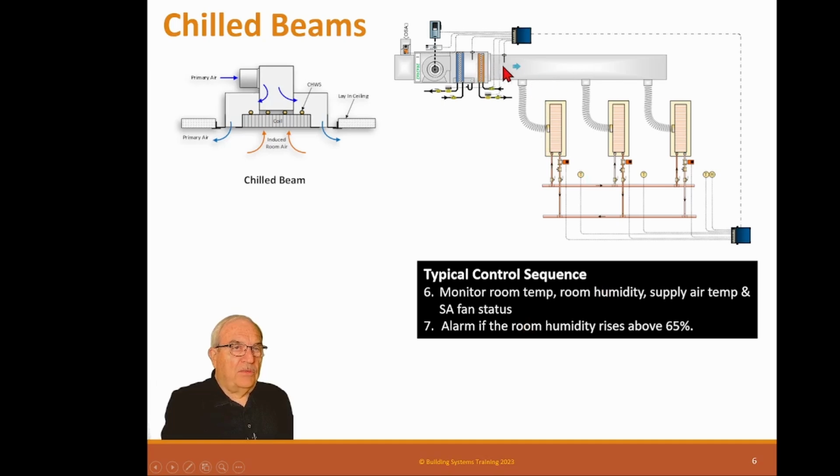Sometimes they have a little bit of a problem setting up the air handler system and how to tab it, because there's no way you can try to measure these little hoses, but these are normally 2 to 4 inch, so they're really small. And the chill beams are not as quiet as the chill ceiling because they have air running across this diffuser, but they're very popular right now. I'm not sure why the engineer chose them, because he has more than one system in the space, but normally you only need one.